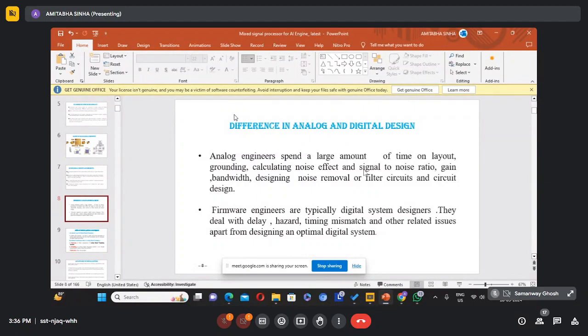If you do that, then automatically the contents of the program counter will go to the memory address register. Theoretically it is okay, but practically, let me tell you, exactly at the time at which the output of the program counter is getting enabled,